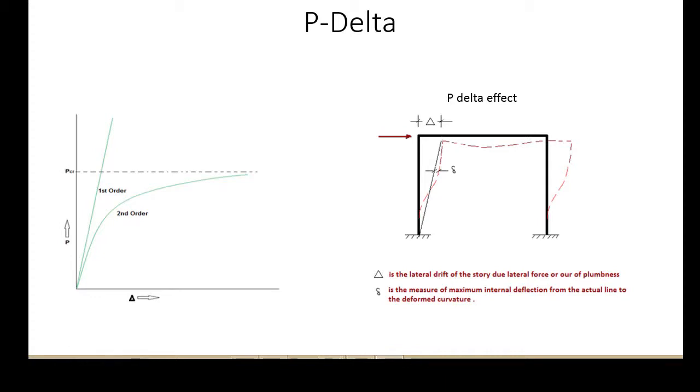As mentioned earlier, the P-delta effect can be captured by performing the first order elastic analysis and then scaling up the result by a certain moment magnification factor. However, one can also perform the rigorous P-delta analysis to capture the exact structural responses. Let's have a glimpse into this P-delta analysis.